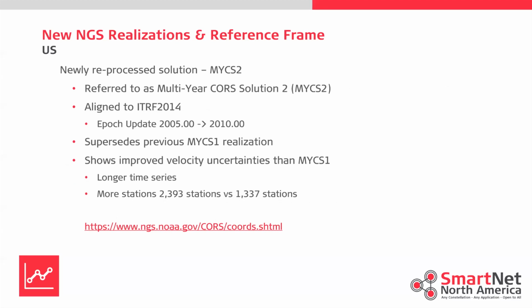So to get into a little bit more detail, the newly reprocessed solution, MYCS2, again, is referred to as the multi-year core solution 2. This is from NGS. This is what NGS has processed to get new solutions out into the market. They've also aligned to ITRF 2014, which was released a while ago by the international community, by IGS, but they're just now adopting it as of September.